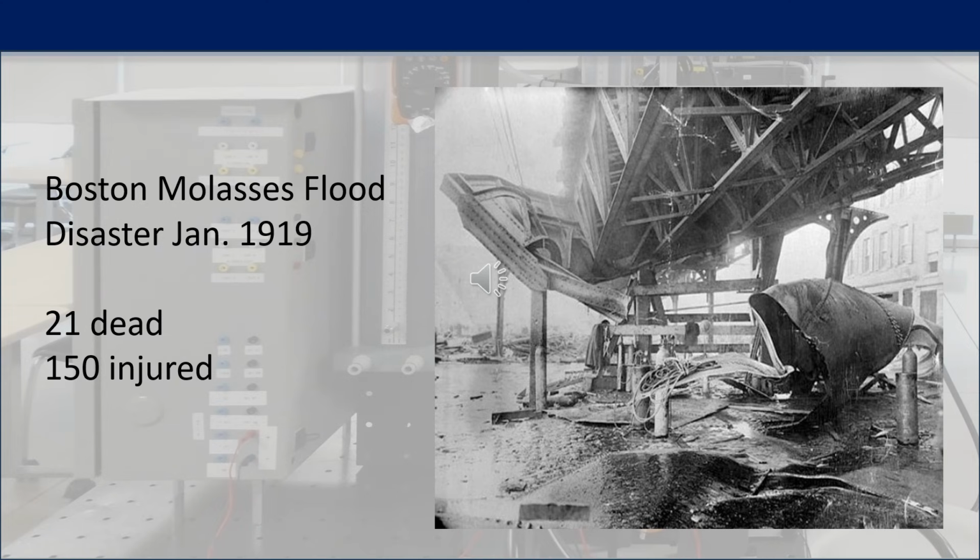We will also examine the inadequate design, construction and testing of the tank, along with the absence of useful pressure and temperature monitoring. No single condition tells the complete story. The disaster occurred when an unsafe vessel, changing process conditions, ignored warnings, and an unusual combination of events all came together. Some consequences were predictable. Others were not. Instrumentation helps us understand those conditions before they combine into something catastrophic.